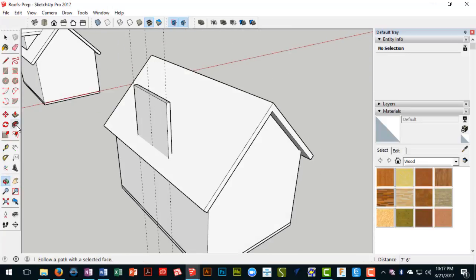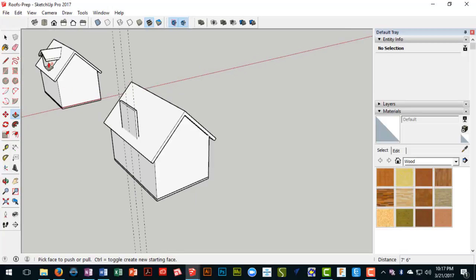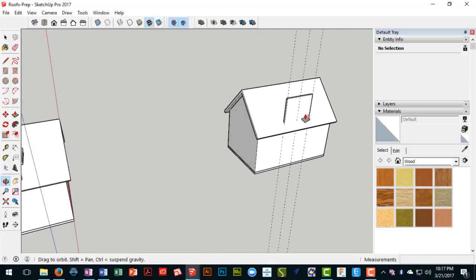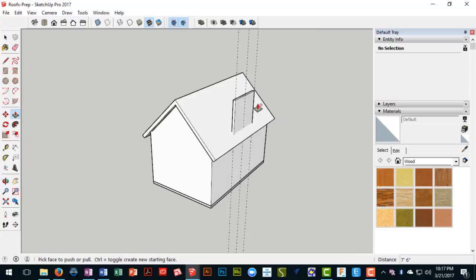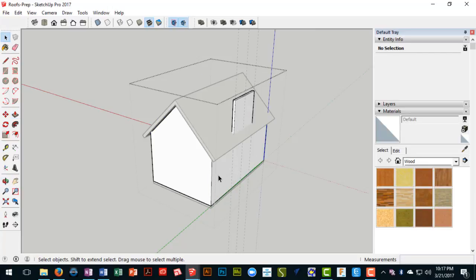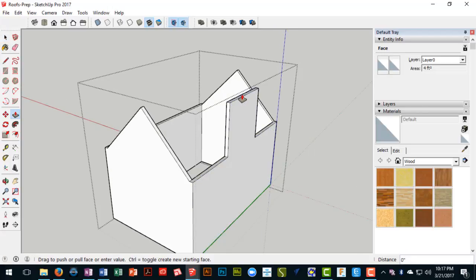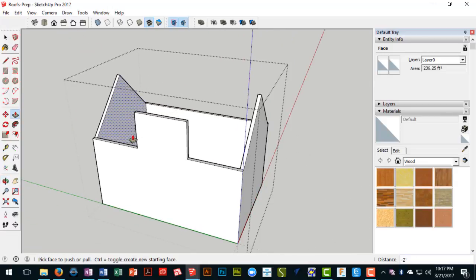And next, we're going to define the pitch of the dormer. So I guess we need to establish the height here. So let's double click on that wall again, hide rest of model, and let's come down. Let's call it 2 feet from the ridge. Okay.